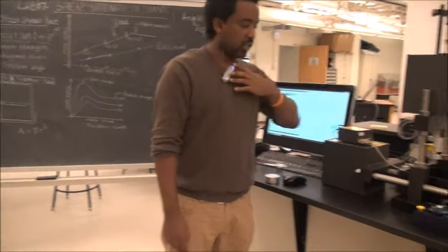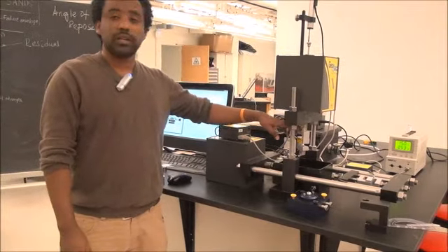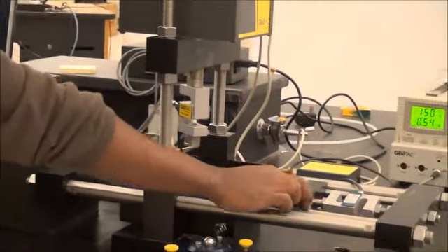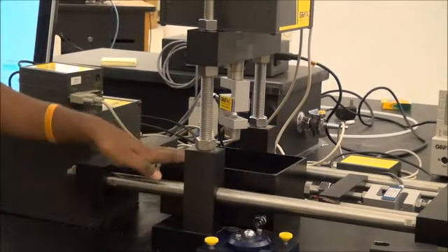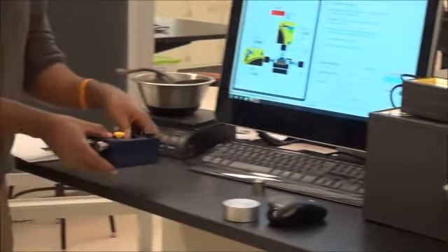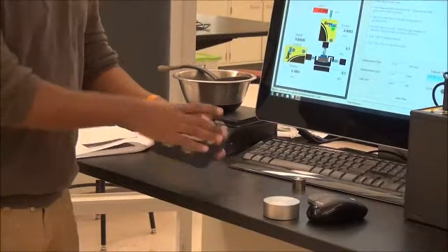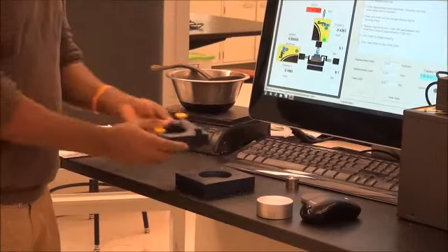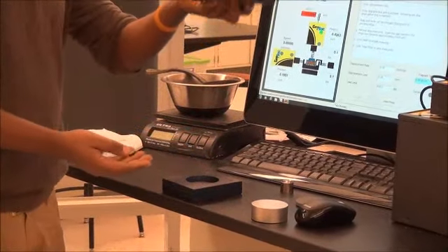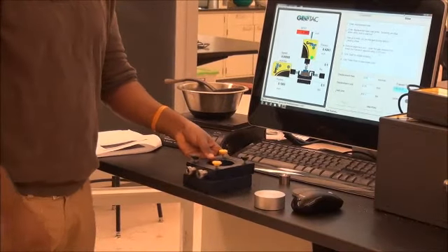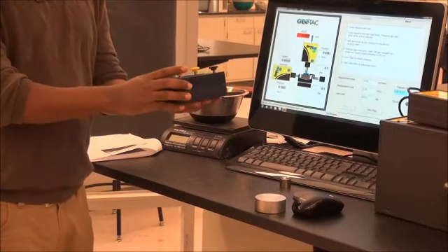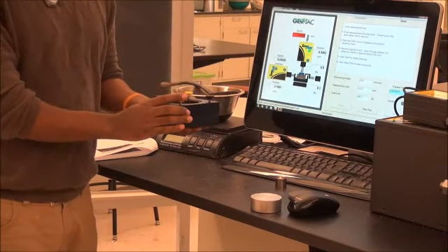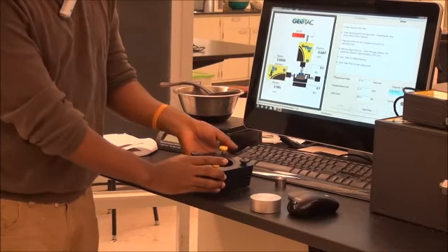This is our test setup, where the normal load is applied through this vertical part and the horizontal load is applied through this one. This is the box where we are going to put our sample, and this is the specimen box, which is split into two. The reason is that it is a direct shear test. The soil is sheared when the bottom one stays in one place and the top one is pushed sideways in order to create a forced shear plane.